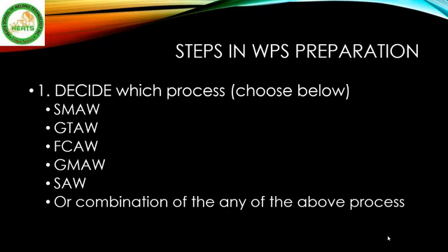There are various steps in WPS preparation. First and foremost, you decide which process you want to use. You can choose from SMAW, GTAW, FCAW, GMAW, or a combination of any of the above processes.